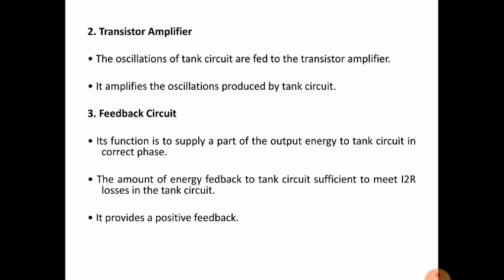So whatever is stored in the capacitor, the reverse voltage, that means the negative voltage, will be applied to the inductor, and then as time continues, the stored energy in the inductor will also start discharging, and the same discharging current will pass through the capacitor, and the capacitor will start charging again. This will continue, the discharging of capacitor and charging of inductor, the discharging of inductor and charging of capacitor, and this produces a smooth waveform, that is positive and negative cycle.